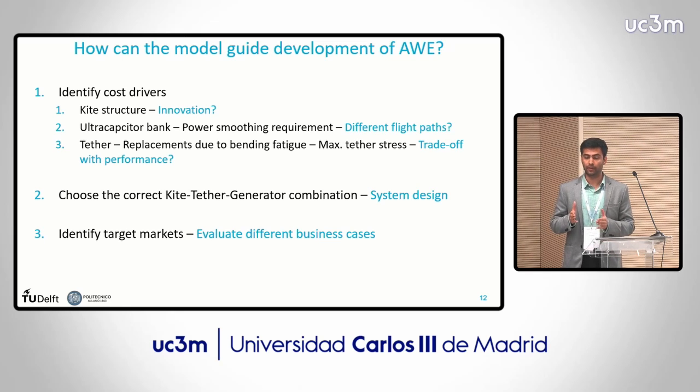The tether replacements due to bending fatigue were high. So maybe now you have to size the tether differently. Maybe you have to use even a larger tether. So you have to trade off performance against the replacements that you need to have. So these decisions really will affect the design of an optimal system, let's say.